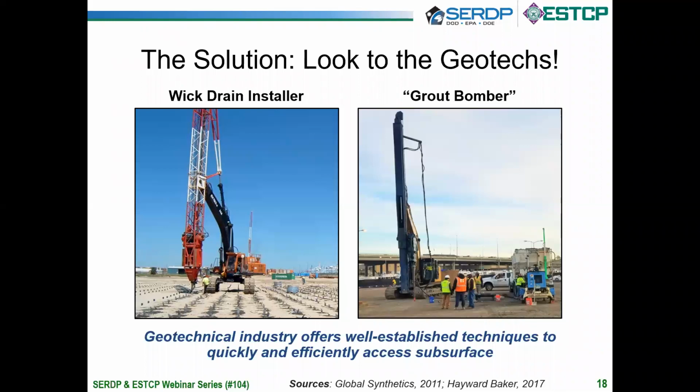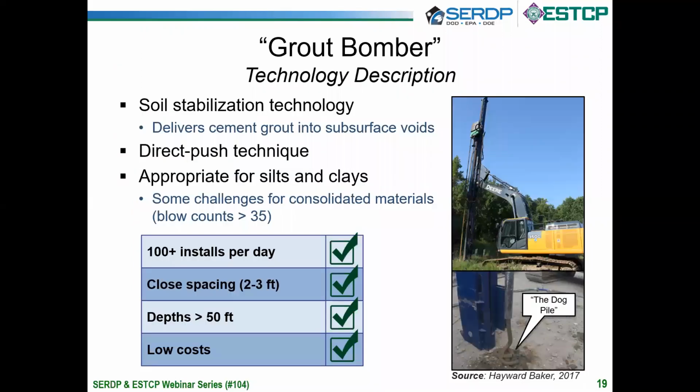So on slide 19, we'll talk about the grout bomber, or simply the bomber. It's a direct push technology that delivers cement grout into subsurface voids to displace and increase the stability of surrounding soils. So in essence, it's not only just filling voids, but it's squeezing native material together to increase the stability for foundations or for above ground infrastructure.